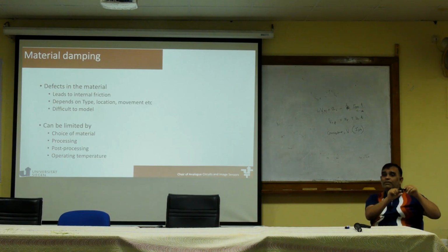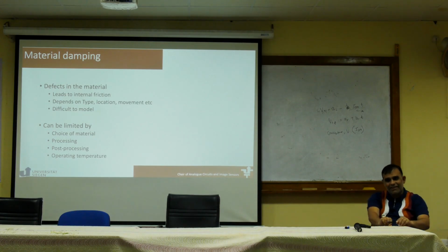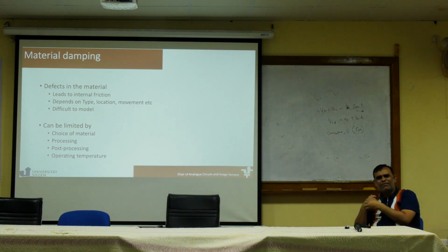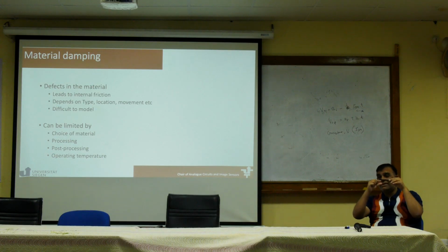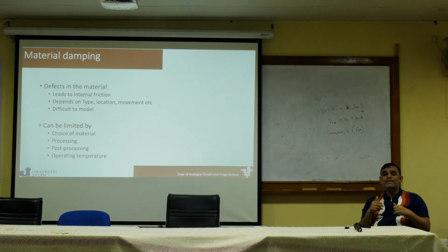And I could not remove that liquid. Whatever I did, I heated it, I took it to low pressure, that liquid just got stuck there and it will not leave. And this area we're talking about is roughly 100 nanometers thick. That's it. It's a very tiny amount of liquid. But for that resonator, it's a solid resonator, that liquid surface, that bubble had very high force that will not allow it to move at all. So forces which we can ignore at macro scale all of a sudden become very important at micro scale.